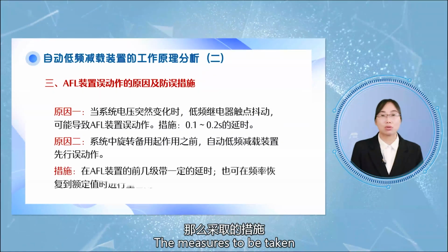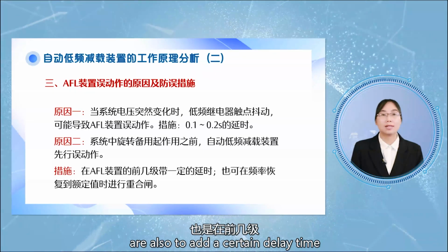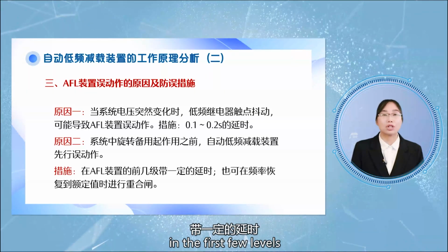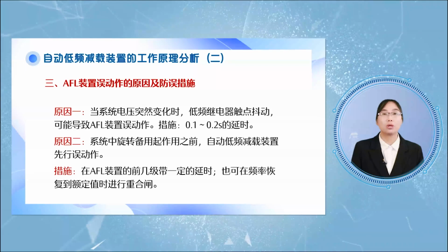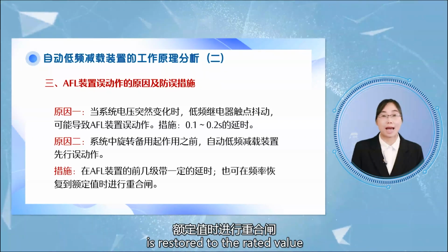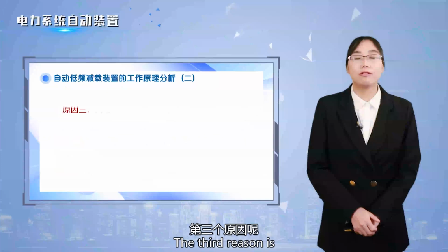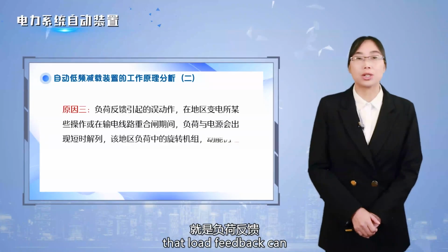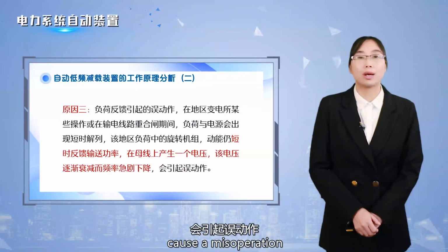The measures to be taken are also to add a certain delay time in the first few levels, or to reclose when the frequency is restored to the rated value. The second reason is that load feedback can cause the misoperation.